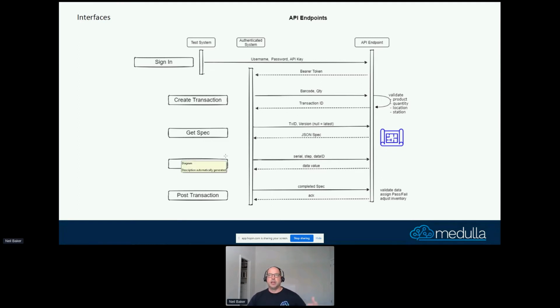So if you do a particular assessment, you check the voltage off a particular pin at an earlier step, that information is stored. At a later step, you might want to use that as input to a calibration routine or whatnot. So you can specify, what was this particular product's performance at this particular step, and you can draw that down from the system.